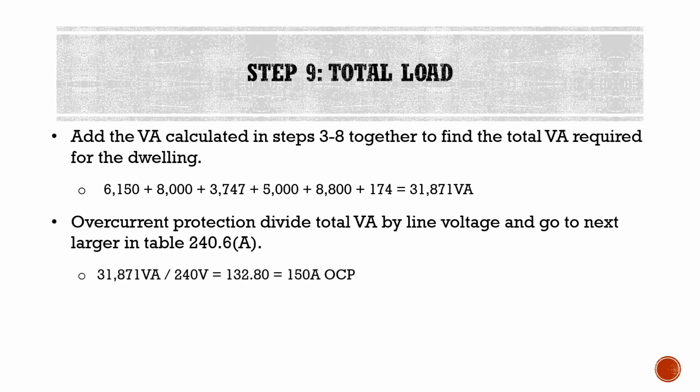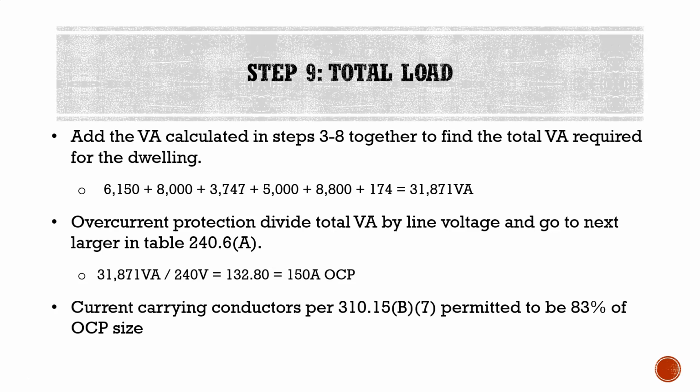So for our situation, we take our 31,871 volt amps and divide it by our 240 volt line voltage, which is standard single phase line voltage in America, and that comes out to 132.80 amps. Looking at table 240.6(A), we see the next larger standard size from that is going to be 150 amps, meaning this is going to be a 150 amp service.